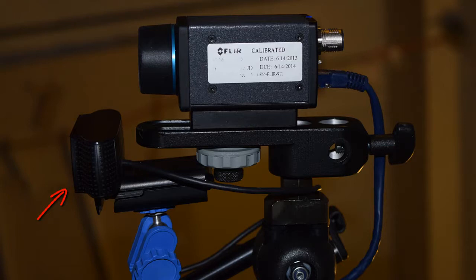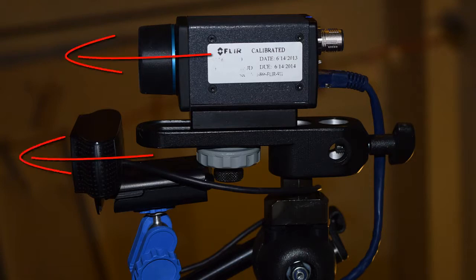So essentially I have two sensors here. I have a thermal one and a visible one. And as you can see, if I draw these lines here, they have different focal axes. So they're off alignment. So if I were to just overlay these images on top of one another, they would, one, not align. And you'll see that here in this image. And then also, there'd be different scales. They'd be essentially not very useful. And so what I'm about to show you is how to actually do sensor fusion.